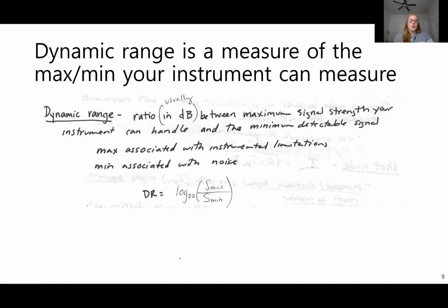So with this dynamic range and the lock-in amplifier that we'll be talking about next week, it's important to know that based on the settings of this lock-in amplifier, the dynamic range changes, and you can overload your instrument very easily with this max setting. So that's why I'm bringing it up now, since it's kind of a transition between the two.